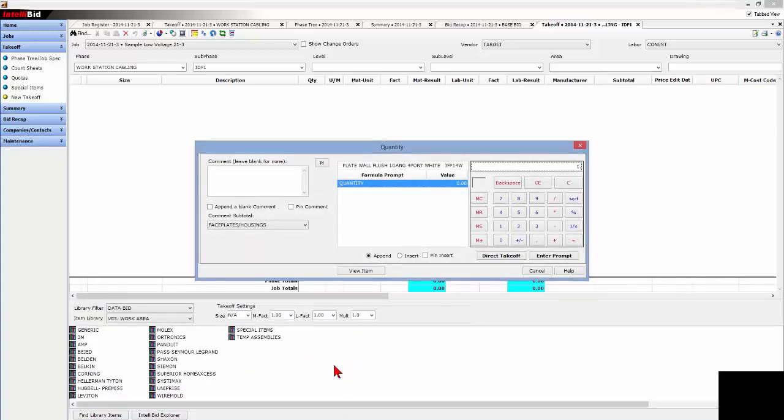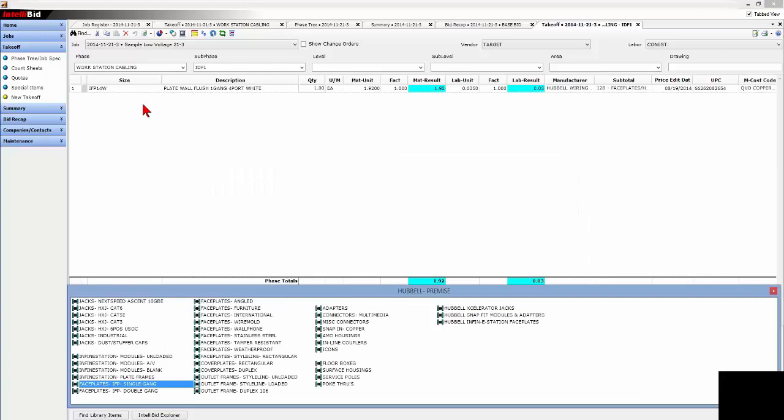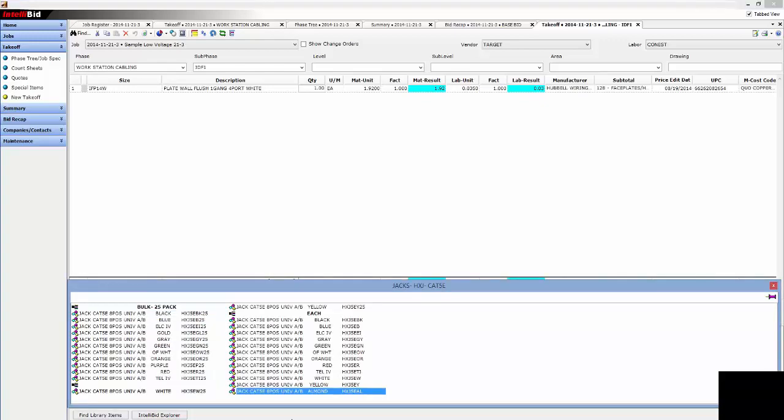Now, a lot of estimators, manual methods, Excel spreadsheets, you would have counted up all these outlets on the drawing and entered 563 outlets. But we're just going to build the individual drop that's required, or the network configuration. So we want a single faceplate. We're going to use a 4-port for design, and then populate that faceplate now with some 5e jacks, Cat6 jacks, as I'd mentioned in our quick specification for the demonstration.